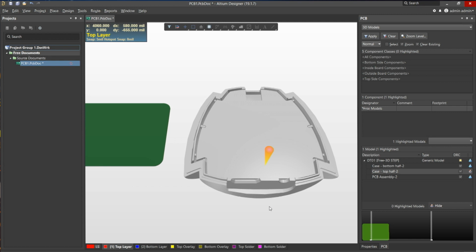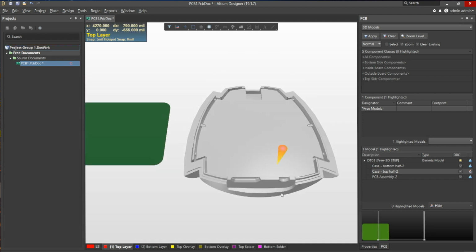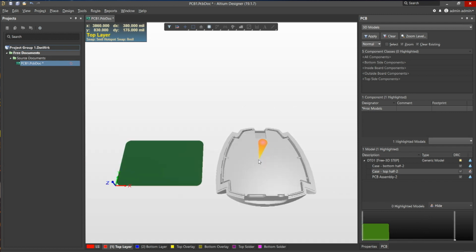Because there'll be a tolerance to the enclosure itself, just wherever you're buying it from. Plastic injection molding is going to expand and retract. You're going to be out a couple mils sometimes. But with your PCB manufacturer, you need to know their tolerances as well. So this is something you still need to communicate to your Mechanical Designer to ensure that they get right.